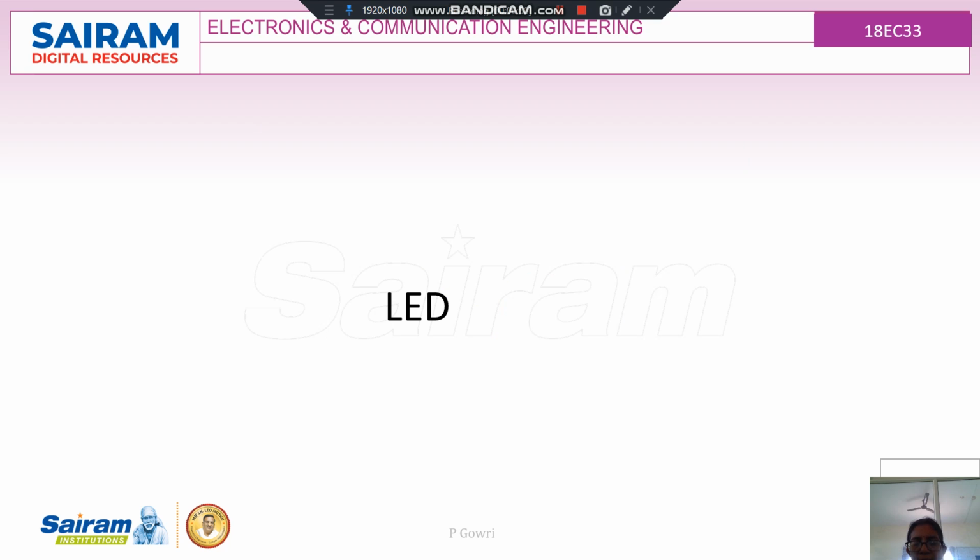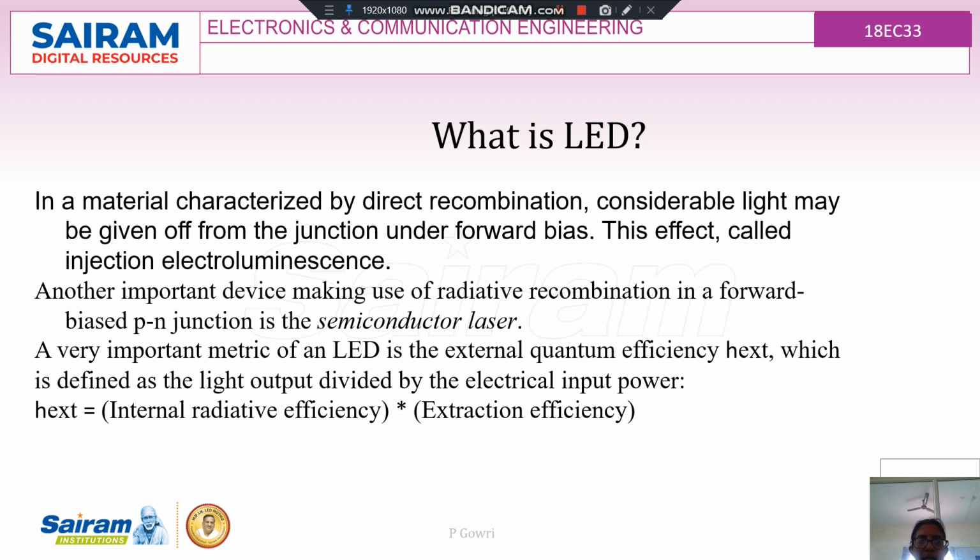So the next one is what is meant by LED. LED stands for light emitting diode. So in a material characterized by direct recombination, considerable light may be given off from the junction under the forward bias. So LED is a device which is operated in the forward biased condition. So this effect is called injection electroluminescence. Another important device that makes use of the radiative recombination in the forward biased condition is the semiconductor laser.